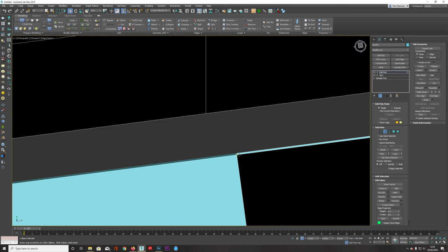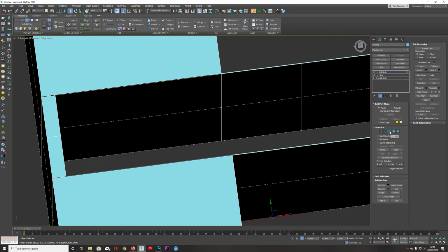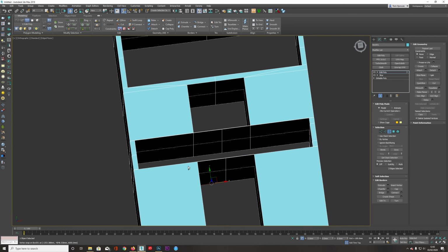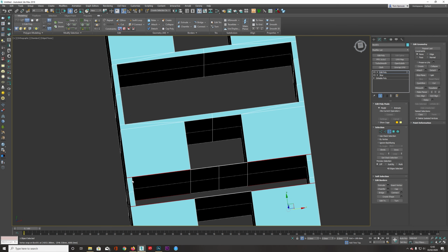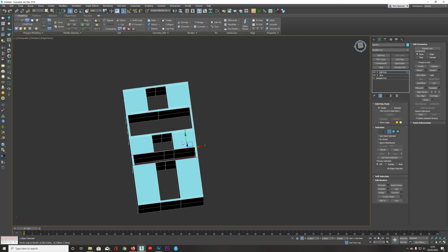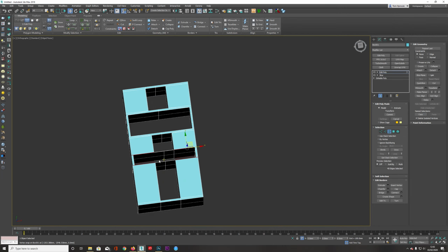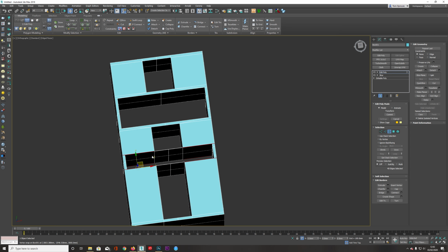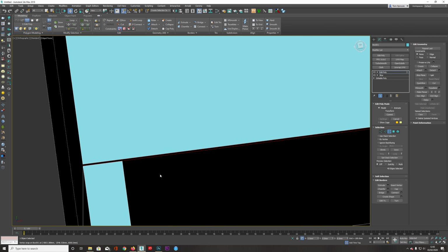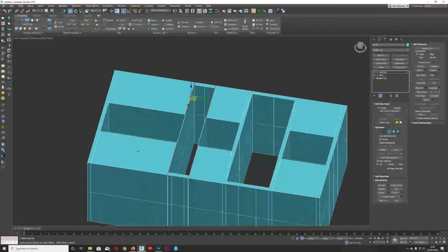Okay, now we've got these covered, and then I can just press 3, which is this border one, press Control A, and the only ones there are these ones here. If you're not sure and you think you may have other split geometry somewhere, you can always take this and move it and just make sure that it's only selected those and something's not moving over here or somewhere else. And then I'm going to just right click and click cap. And those are now capped.